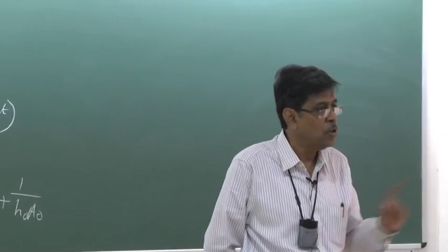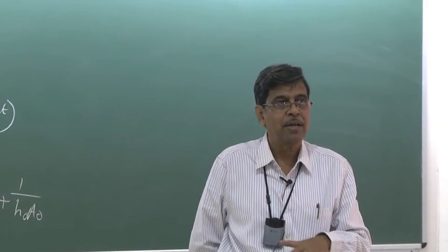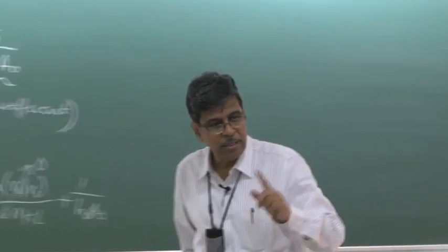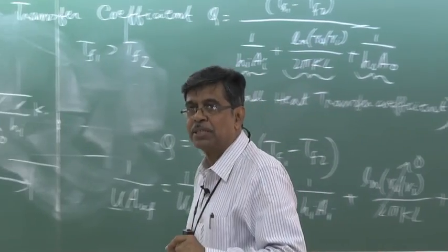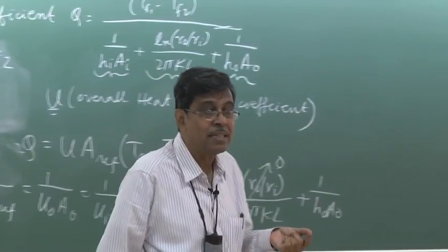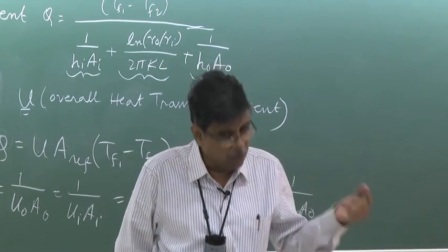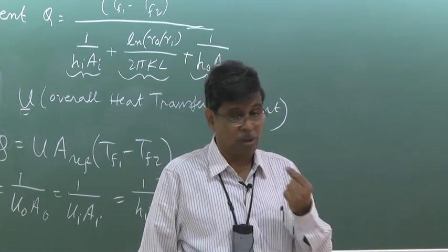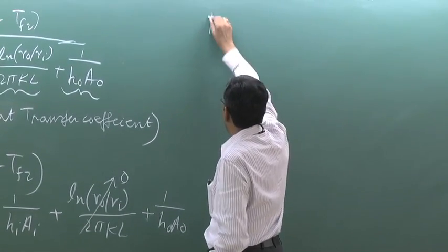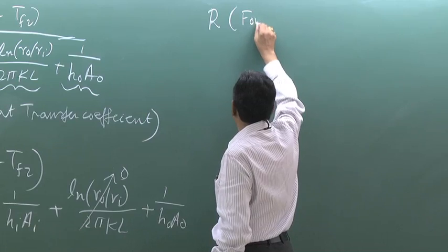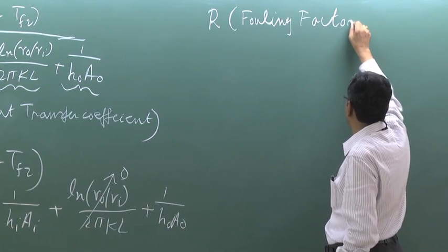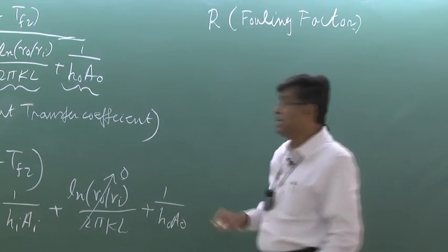These are known as scales, not our geometric or dynamic scales of our theoretical analysis. This scale means a formation of thin coating. The impurities get coated and make a scale formation. Physically, that puts an additional thermal resistance to the heat flow, both inner side and outer side, because of the scale formation due to impurities. And that is expressed by a fouling factor denoted by R. R comes from the resistance. This fouling factor is expressed in terms of a resistance R, which is defined as,